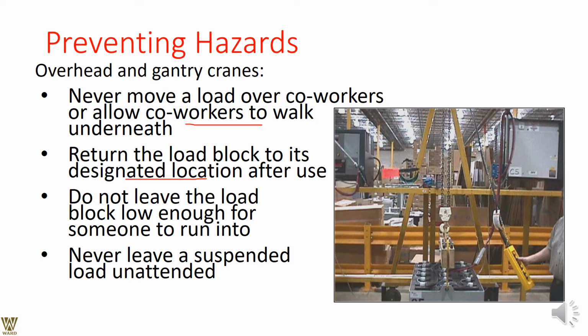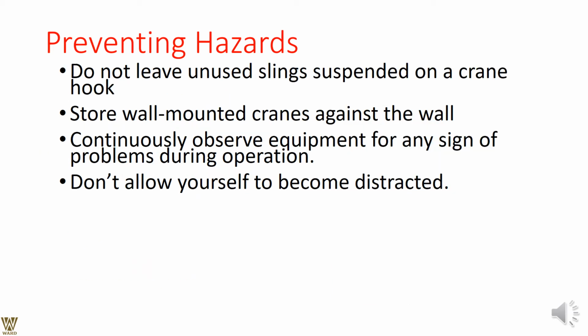Do not leave the load block low enough for someone to run into. Never ever leave a suspended load unattended. That is what we are looking out for, and we should not be looking into such activities at any point. Preventing hazard: do not leave unused links suspended on a crane hook. Look for wall-mounted cranes, which are much better. Continuously observe equipment for any sign of problems during operation, any malfunctioning, any noises coming. Don't allow yourself to become distracted.